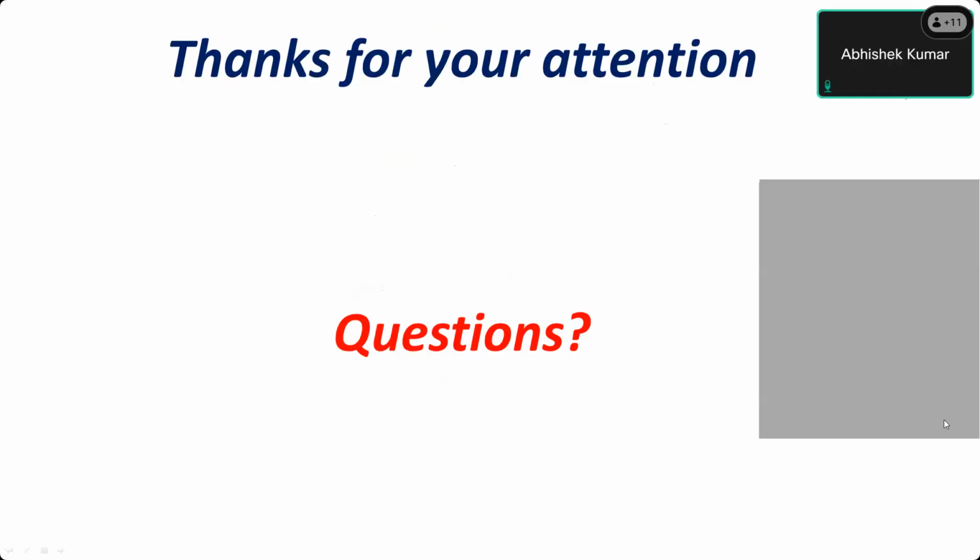Hello, Dr. Hesham. Thank you for this wonderful presentation on GPR and its application in various subsurface studies. I have three questions. The first is that, as we read about GPR, EM velocity is dependent upon the relative dielectric permittivity, RDP. The attenuation depends upon the conductivity and frequency that we use. So it is also true that if there is a high water content in a soil, then it will impact both RDP and the conductivity, right? So is there any relationship between RDP and conductivity? Can we calculate conductivity directly from the RDP?